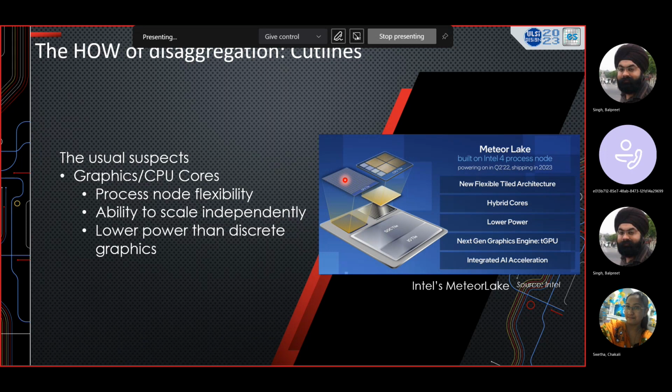So when we say chiplets, are we always talking about 3D stacking or on the silicon interface? Yeah, I think City talked about it. That is also another way of doing it. It's what we call 2.5D. And if you are doing it on top of each other, it's 3D. It's just naming, but many companies go to 2.5D and 3D. 2.5D is connectivity through a silicon interposer. I think the Ponte Vecchio example that he gave, with about 47 chiplets, had both 2.5D and 3D.